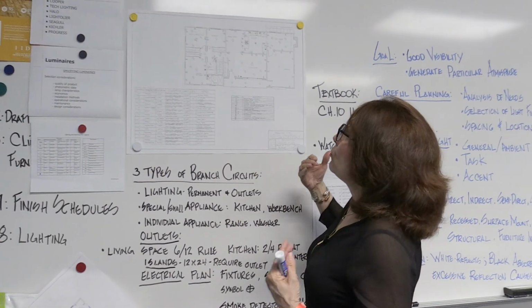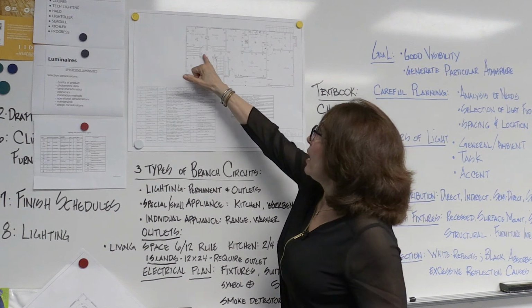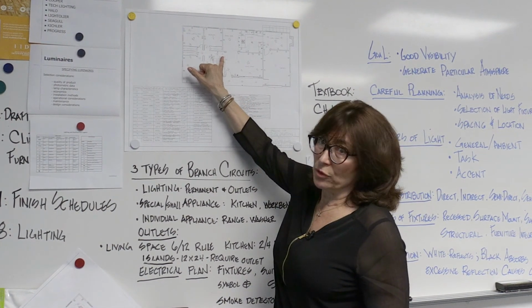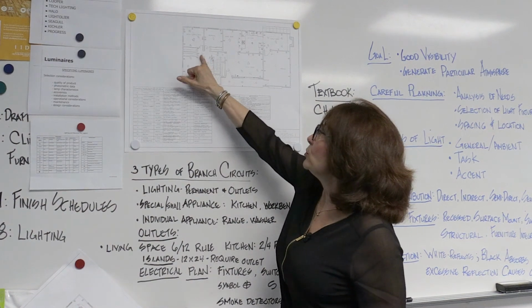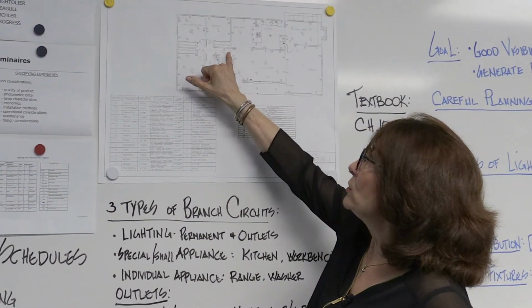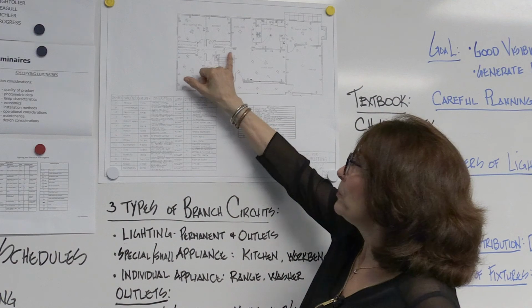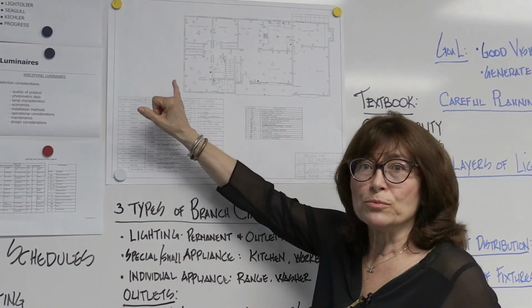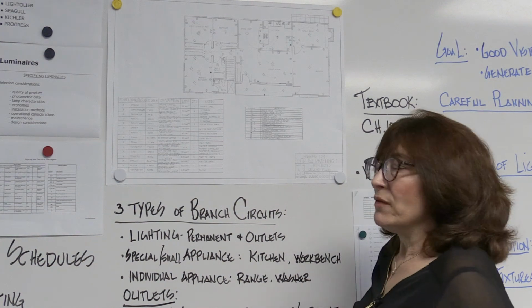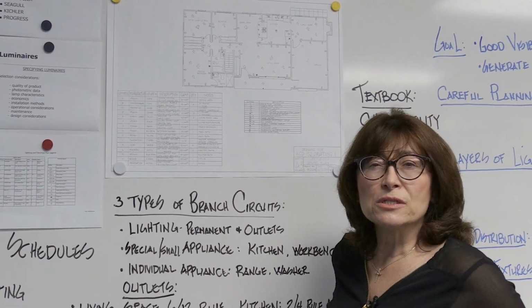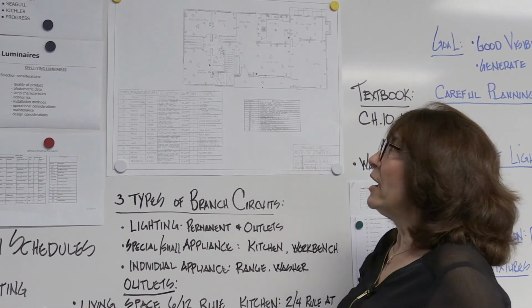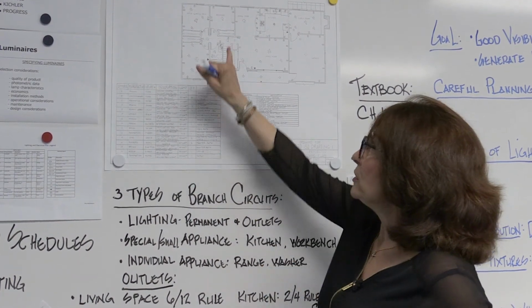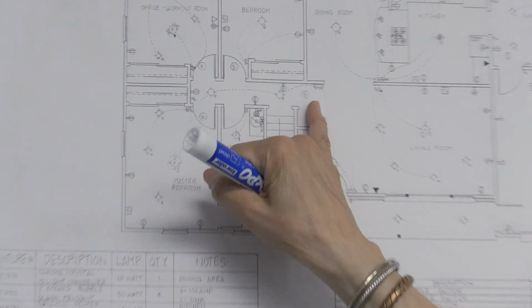So what you want to do is have one that is within 10 feet of a bedroom. That's on the outside of the bedrooms. You must have a smoke detector within 10 feet. I also put one in every one of the bedrooms, because if you have the door closed and you're a very sound sleeper, you want to make sure you have extra precaution. So you want to make sure that you get a smoke detector within the bedrooms, within 10 feet of the bedroom.